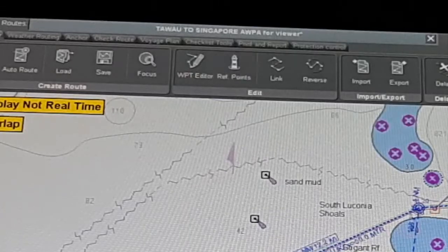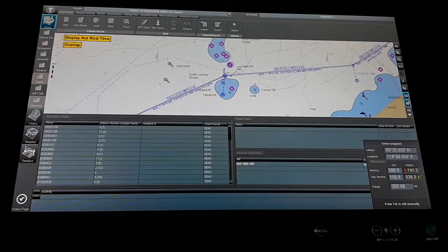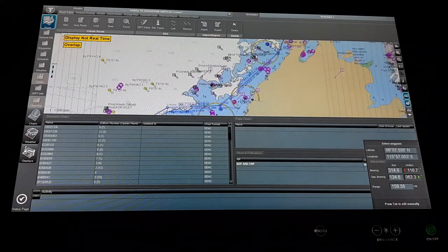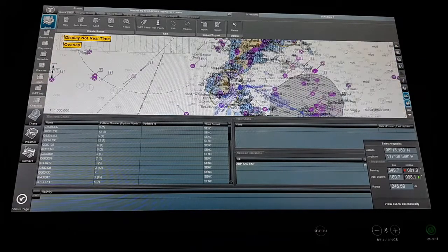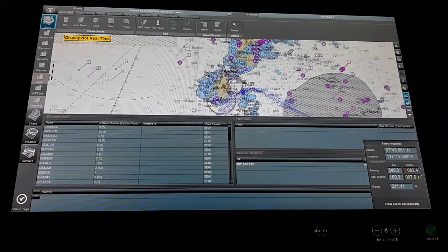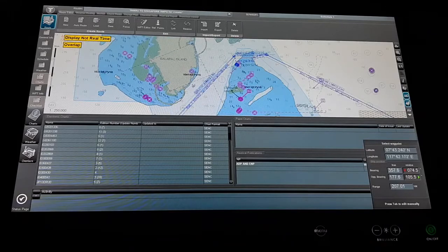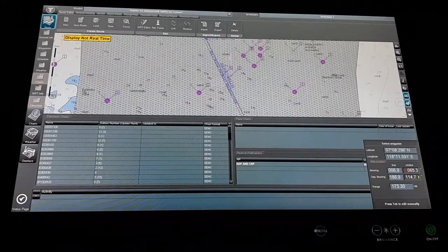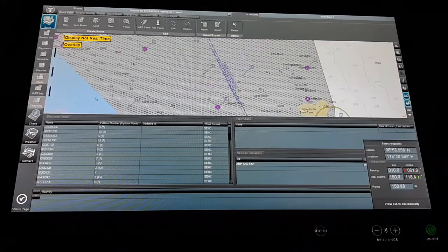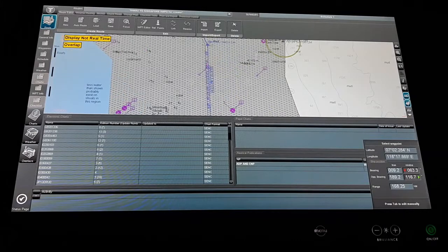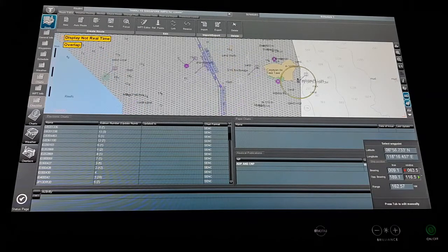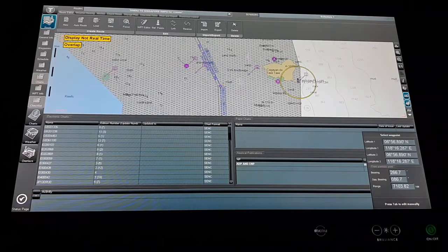After that we have the reference point. A reference point we normally take from any fixed object, any landmark or lighthouse, not actually from a buoy, or maybe from land, because the buoy is also floating. So that's why we normally don't take a reference point from a buoy. We normally take it from a fixed object, mostly a lighthouse or any beacon or land nearby. Suppose this can be a reference point.